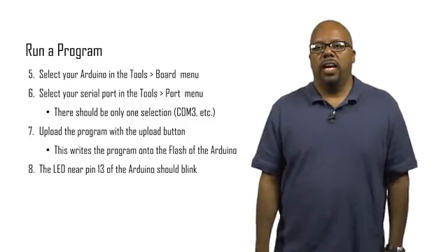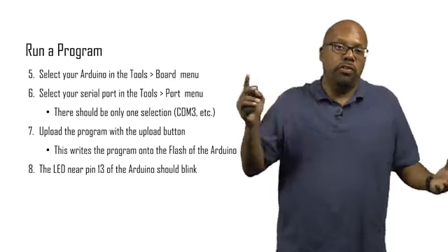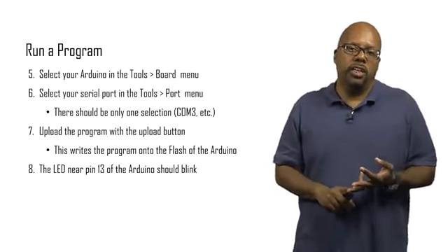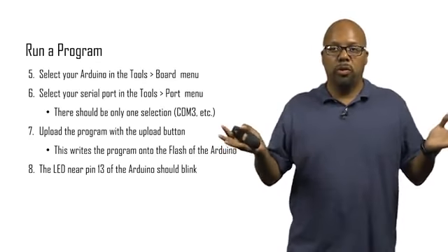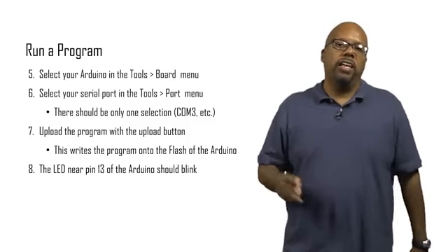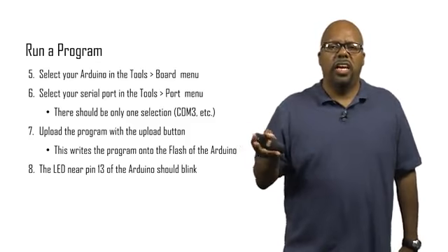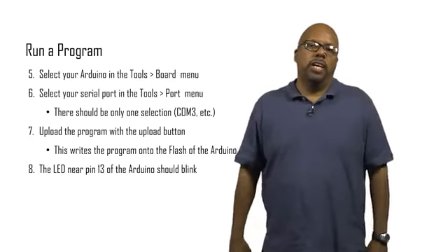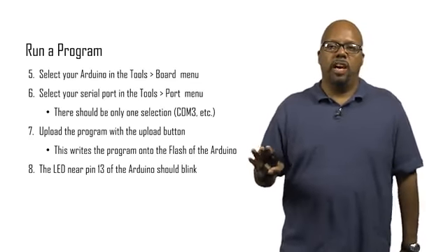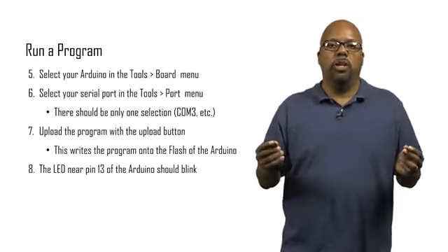Once you've selected the serial port, you upload the program. You press the upload button on the IDE. It'll compile the program, checking for errors, and the Blink program will have no errors. It'll compile it and then upload it. That'll take several seconds, ten seconds, let's say. Some lights will blink on the board quickly, and then they should stop blinking, and it should be programmed. You should see a little message that says, done uploading.